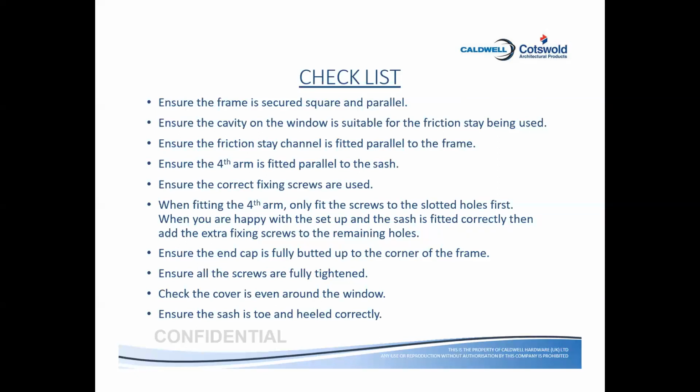And if it is vice versa, if suppose the cavity required is 16, 17 and you used a 13, 14 arm, then it is required to use the packer. If you don't use the packer, there will be a gap from the top, especially in side hung. And if it is top hung, there will be a gap from either side based upon your geometrical fixation.